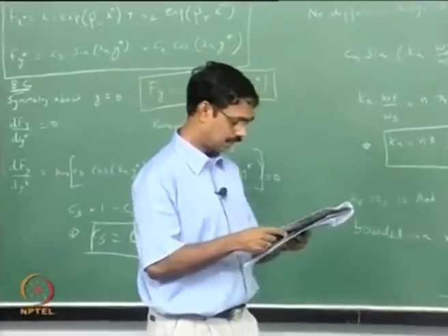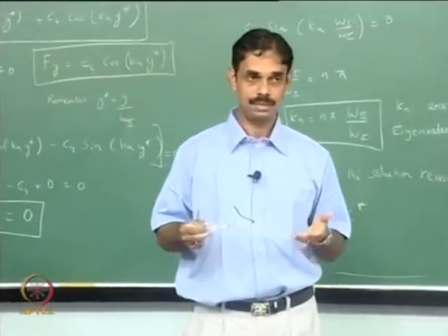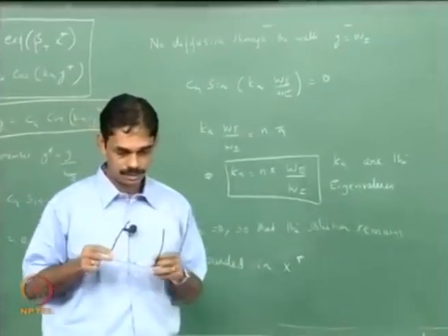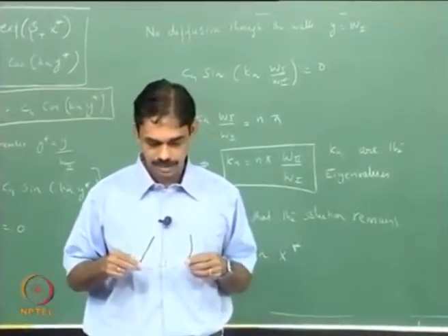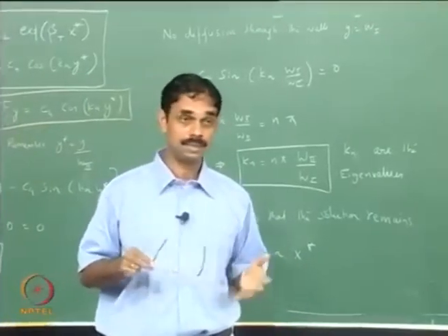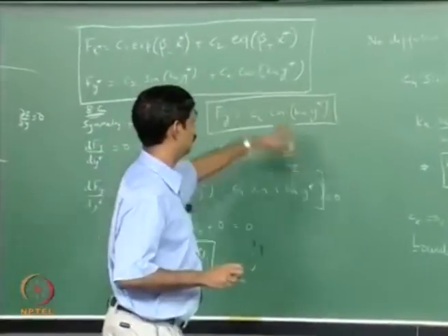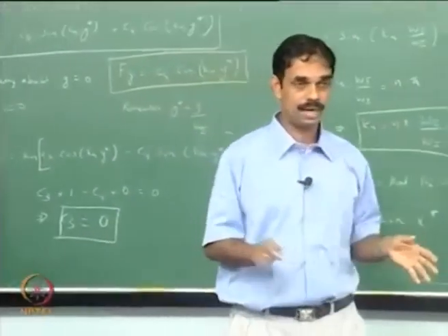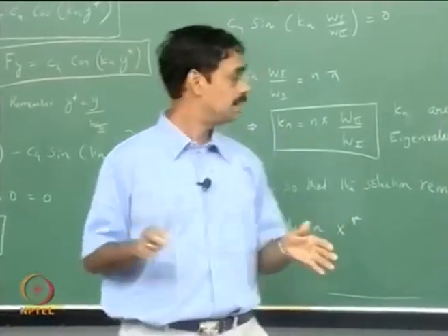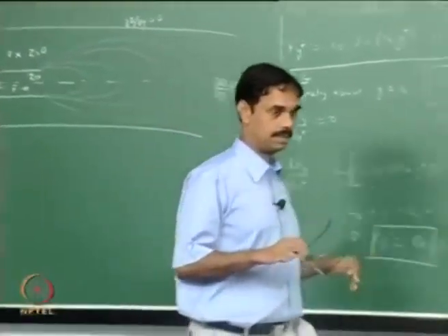Since kn takes infinite values, there is no upper bound on what n is. So the solution to Z0 is an infinite sum over all integer values of n with coefficients which are like this, C1 times C4. These coefficients, and we are adding n number of them, have to be solved using the boundary condition at the inlet plane. Okay, so it's clear, right?